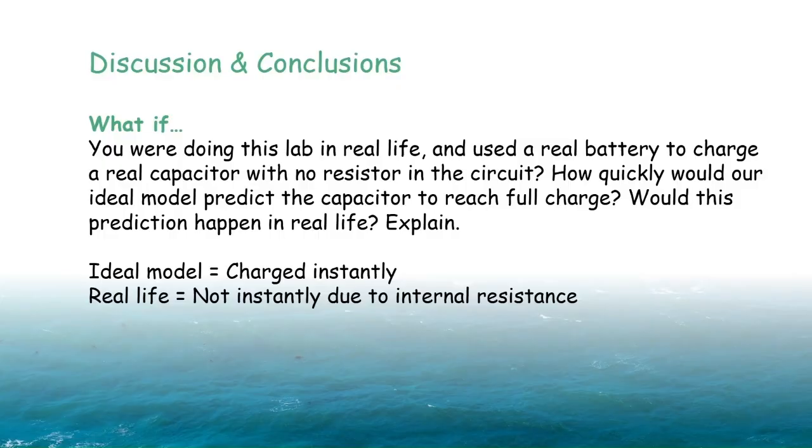So what if we used an actual battery and no resistor? Our ideal model would predict that the capacitor is charged instantly, which would not happen in real life because there is some internal resistance in actual batteries.